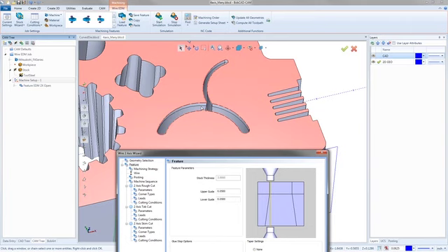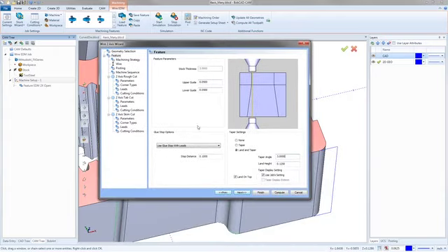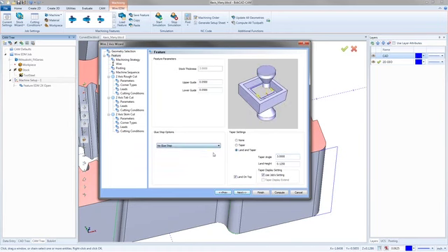You'd actually not want to pick the top. You'd have to pick this edge here so it knows to kind of taper away from there so you're not screwing everything up. So I'm going to leave it for the land and taper. No glue stops. I don't need that stuff right now. We got the land on top. If you wanted the land on the bottom, you would click that button there.